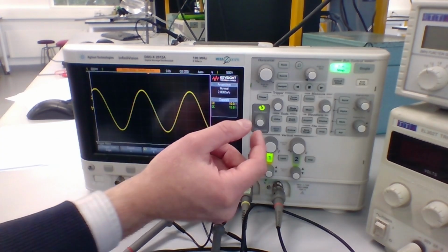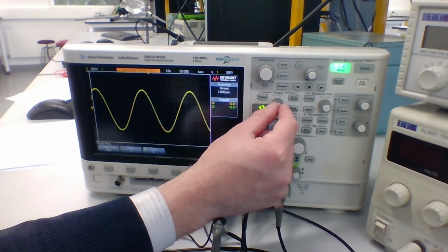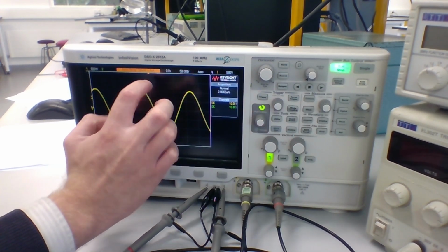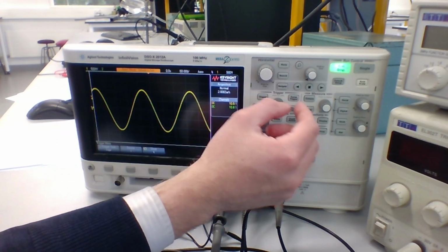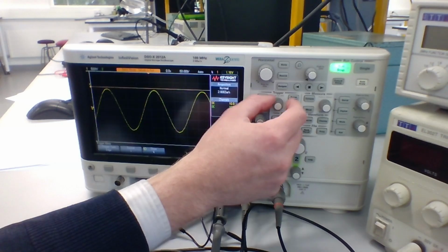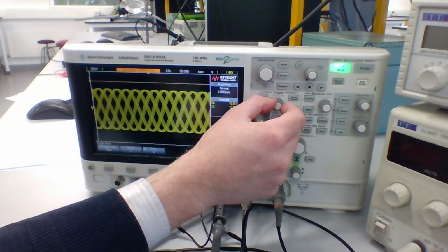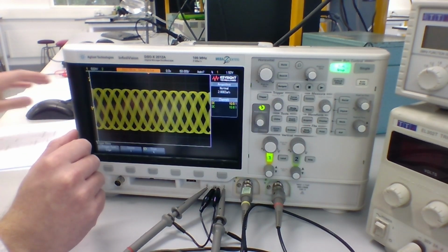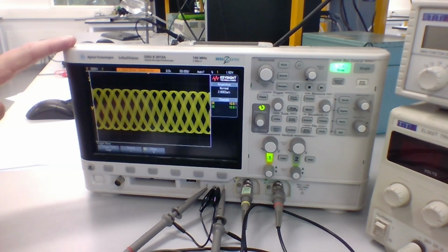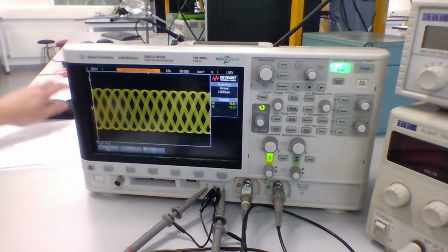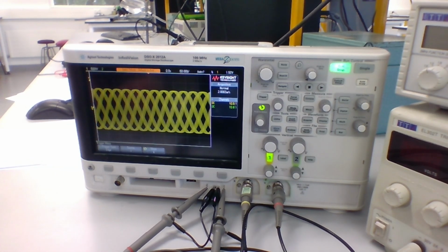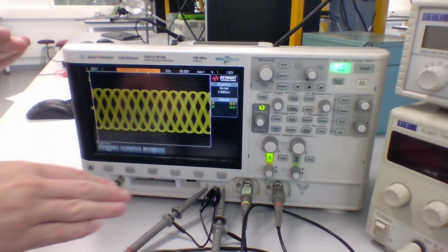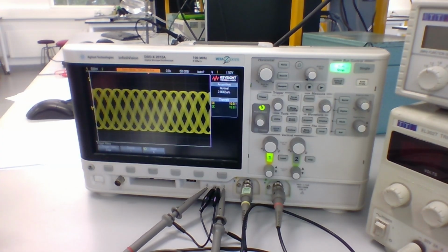Okay. The next thing we're going to do is increase our trigger voltage until it is larger than the waveform we're measuring. So we were instructed to set it to 1.5 volts. So let's dial that to 1.5 volts. At the moment, the scope is now doing what's called auto triggering, and we see quite a mess on screen. By default, the oscilloscope will be in what's called auto triggering mode. Basically, what happens is that it'll first of all check the trigger level against what it's measuring and see if it can then take a measurement based upon that.